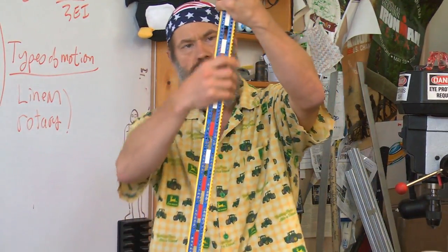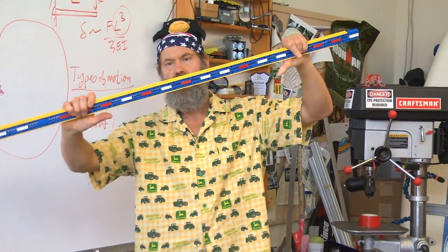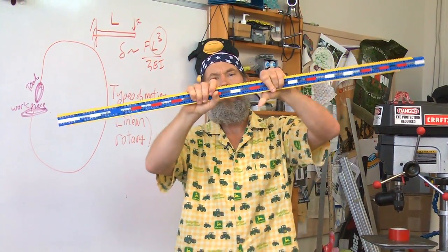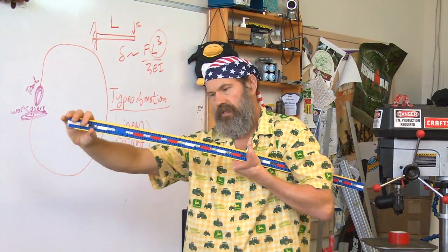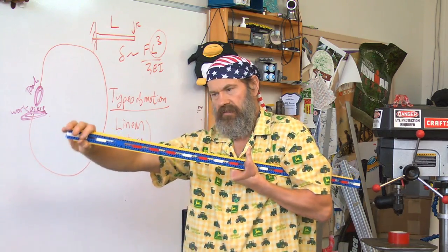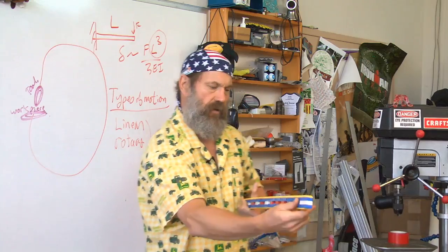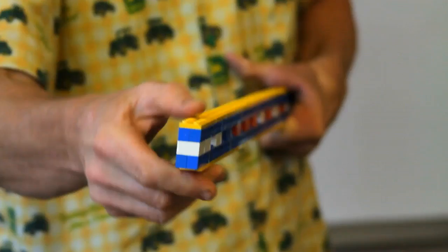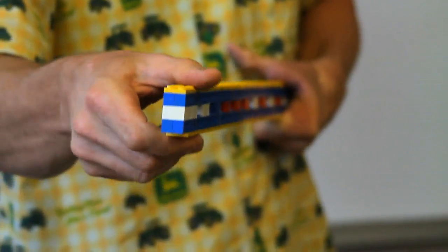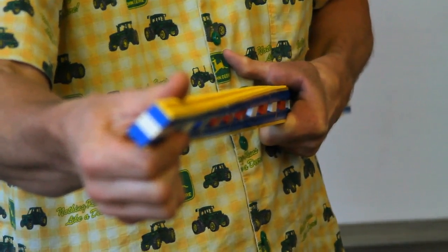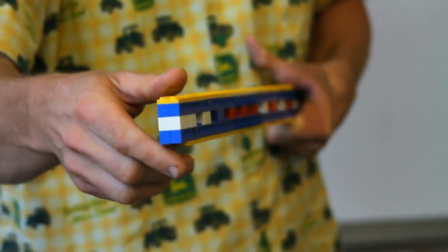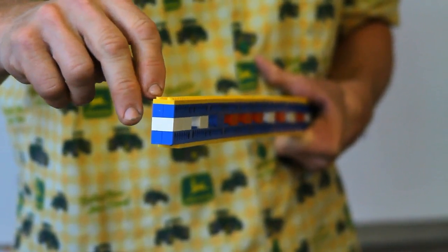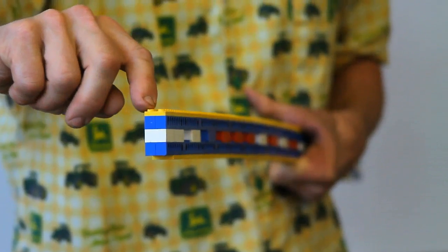This looks like a beam made out of Legos, yet it's fairly flexible. Yet close up, it's pretty stiff. See, when it's long, though, is when it gets more compliant. And watch what happens now also. It's actually pretty stiff given it's Legos. But see how soft it is in this direction? We're going to talk about the torsional ability of structures. And because it's soft in torsion, remember, torsion is force times distance. What happens when this beam is loaded symmetrically, but if I load it off-center, watch what happens.